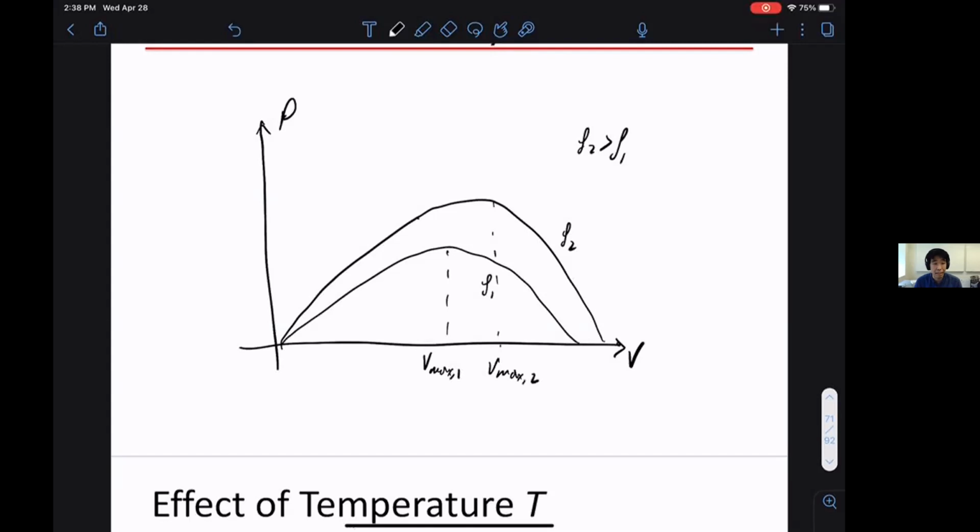Based on what the irradiance is, to generate the maximum amount of power, you actually have to change the voltage. At every time instant, there's a feedback loop inside your solar cell that measures the current coming out of the cell and then tries to adjust the voltage to maximize the power.